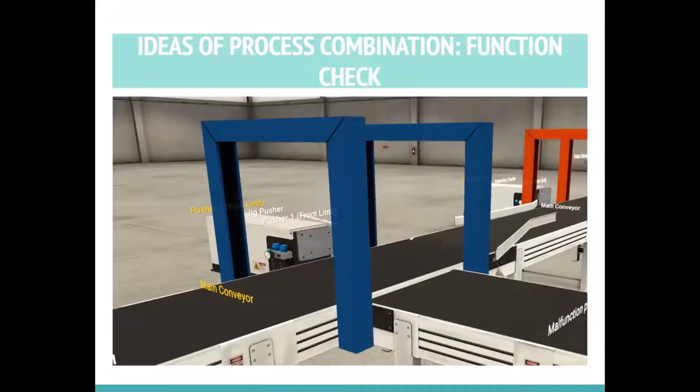For simulation purposes in Factory IO, however, we have designed a setup that mimics the function to check for tolerances like an inspection jig, in particular the function to check for product dimension, height. In this simulation, we have used a capacitive sensor. However, for actual application might be different. But it stands to reason that this setup is only made possible because we have chosen a Lego piece as our product for this particular proposal.